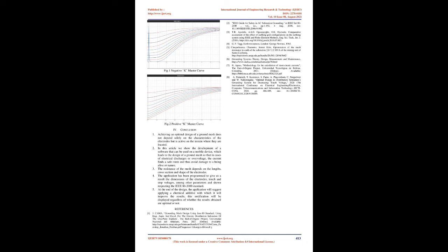It is necessary to comment that k varies between -1 and 1, that is to say that for k values between -1 and 0, results of ρa/ρ1 greater than 0 and less than 1 are obtained, which corresponds to the fact that the first layer has a resistivity greater than the second. For k values between 0 and 1, the values of ρa/ρ1 will be greater than 1, since the resistivity of the second layer is greater than that of the first.